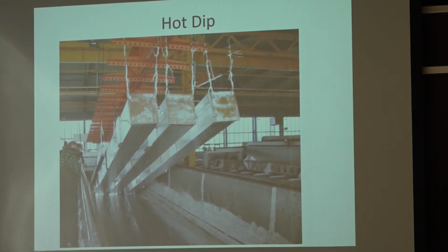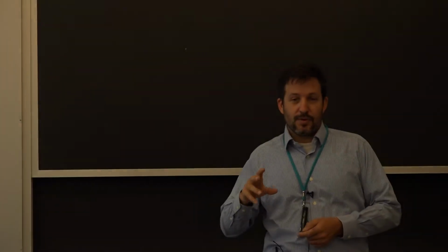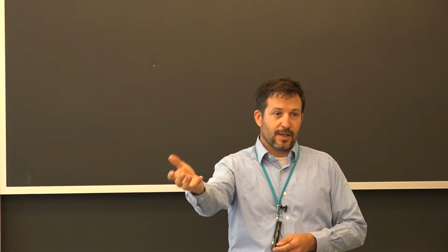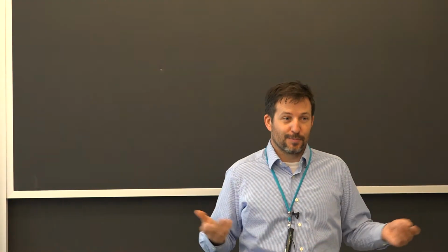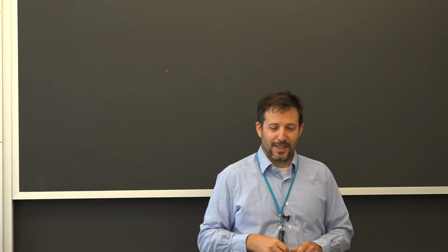What becomes an issue a lot of times is trying to put paint on the galvanizing. That's why in a lot of stores and on the highway you'll see galvanized guardrail, for example, where you see the grains, so you know it doesn't have anything more than the zinc coating. One reason is if you try to put paint on it, a lot of the time it's going to fall off, so it looks worse than not doing anything.